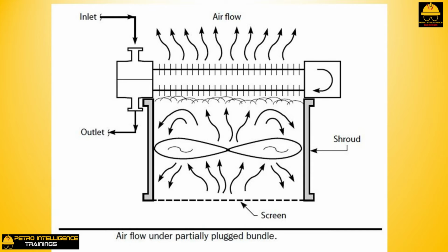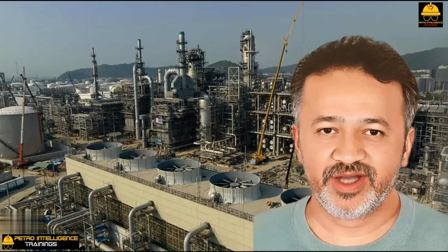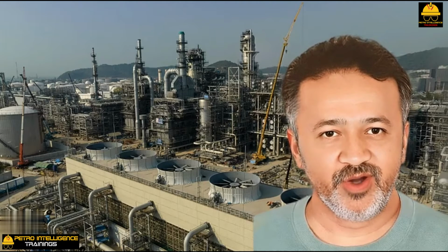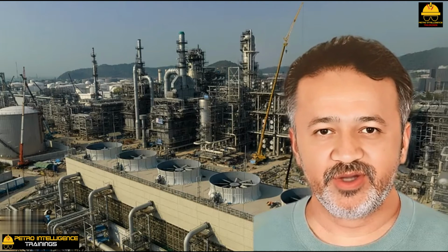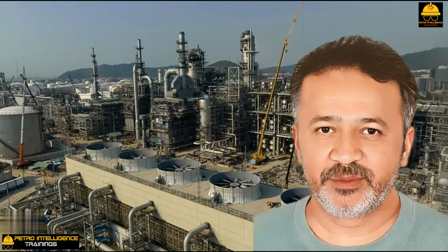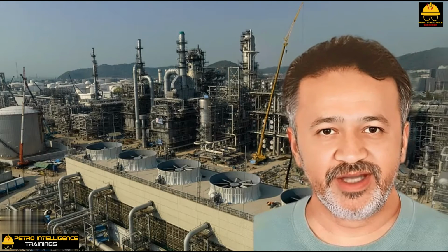Take a close look at the picture. Note that on the right side of the sketch there is a small gap between the blade tip and the shroud. It is this gap that accounts for the air recirculation previously described. The bigger the gap, the greater the detrimental air recirculation. With age, shrouds get out of round and the gap increases, but not uniformly.